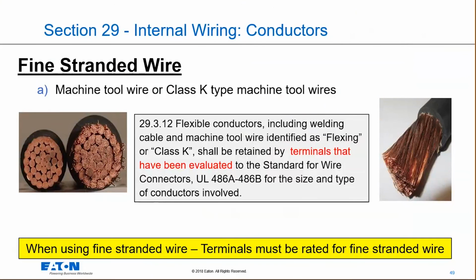So take a look at your component, whether it's a contactor or fusible switch or whatever it happens to be, and make sure those terminals are rated to handle that particular wire, whether it's stranded, solid, or fine stranded wire. That seems to be the most common hiccup.